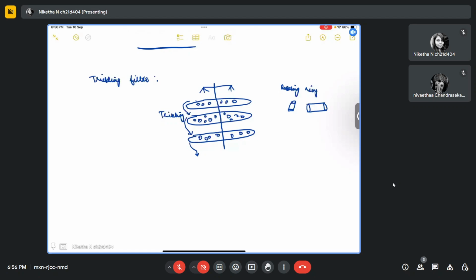So when we supply raw wastewater at the top, whatever Raschig rings or whatever particles are there, because of the bacteria present in the inlet raw wastewater, they will grow a layer of bacteria. Okay, so imagine this is the surface of the Raschig ring. Over this, a layer of bacteria or slime will grow.